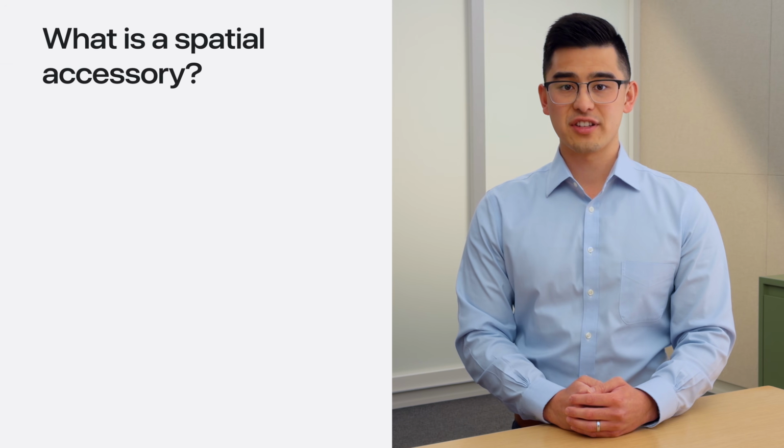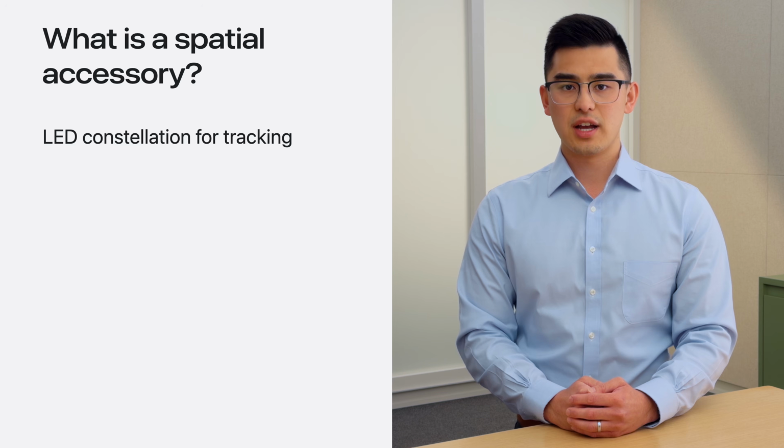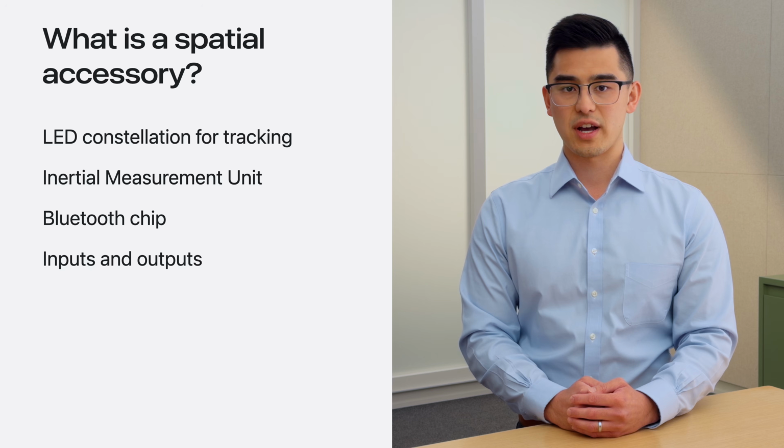A spatial accessory is an electronic device which must contain a board with the following components: a constellation of LEDs visible to Apple Vision Pro for tracking, an IMU to capture the orientation and acceleration of the accessory, and a Bluetooth chip to send the signals to Vision Pro. Spatial accessories can also host any variety of inputs, including buttons or a touchpad, and outputs like haptics. Any accessory that has these key components is compatible with visionOS.